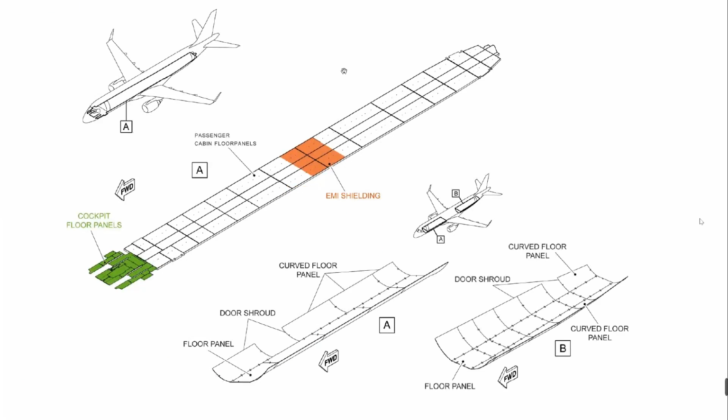Have a look. Cockpit panels, because below we have forward avionics. Here in mid cabin, below we have the middle avionics compartment. Again, the aisle panels in the cabin are a little bit more specific because they are high loaded. Same with the forward and the aft galley areas. They are a little bit more specific. The panels which are under the passenger seats are not so resistant to the weight.